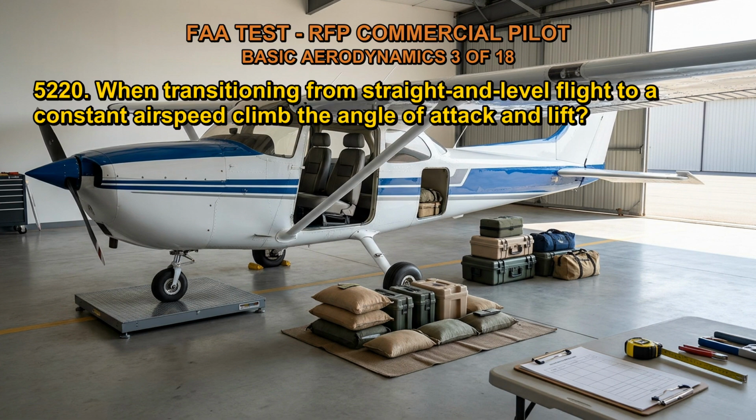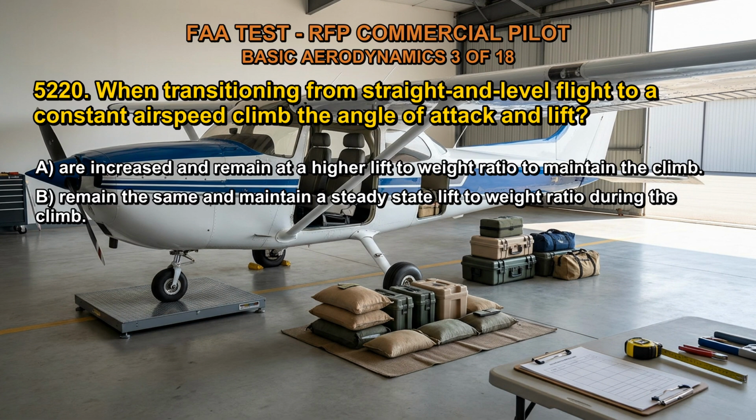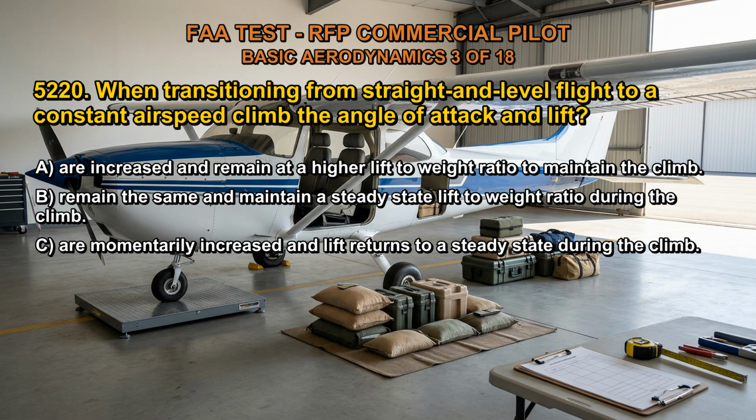5220. When transitioning from straight and level flight to a constant airspeed climb, the angle of attack and lift. A. Are increased and remain at a higher lift-to-weight ratio to maintain the climb. B. Remain the same and maintain a steady-state lift-to-weight ratio during the climb. C. Are momentarily increased and lift returns to a steady state during the climb. The correct answer is C.